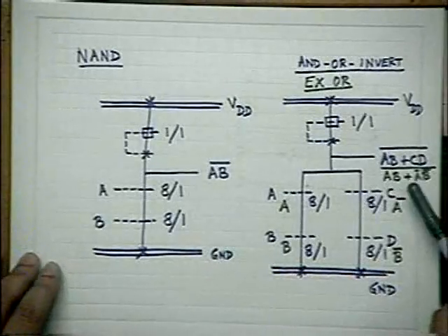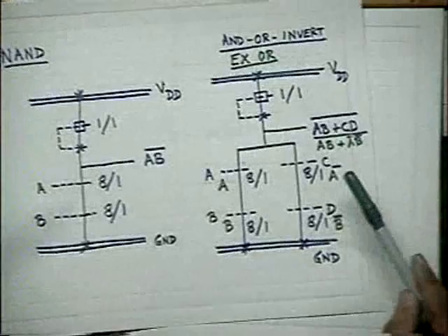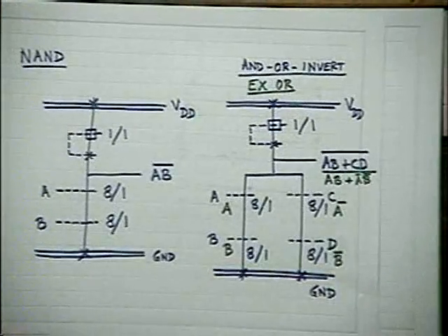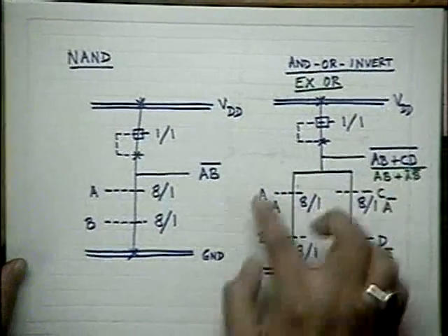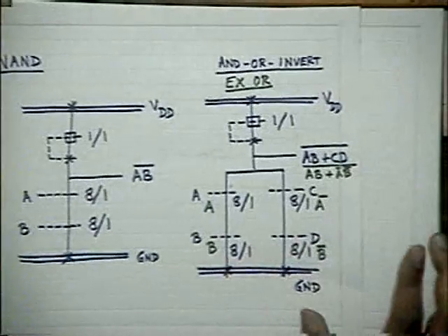At the input I/O circuit, on the input side, this is done. It is standard practice. So don't worry about A inverse and B inverse, the complements. They are readily available. So this is the most compact form. If you want to use the conventional A B bar plus A bar B, inverted, then naturally another inverter will be needed. So we avoid that.